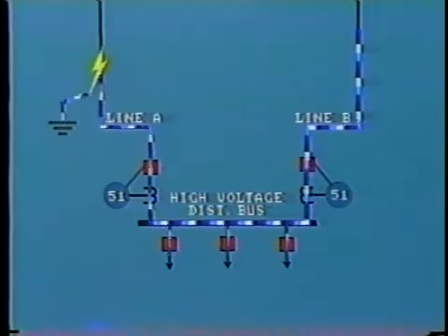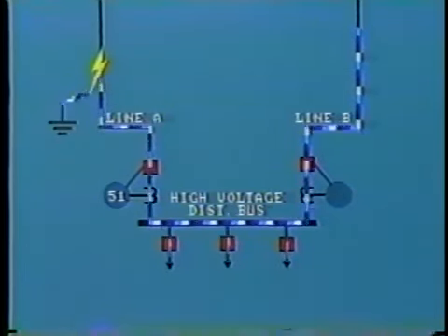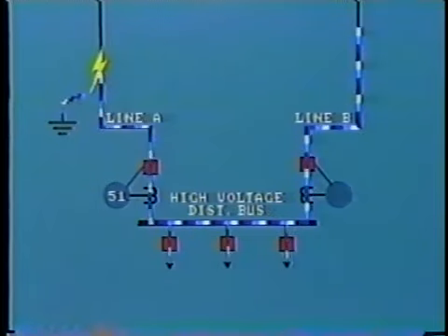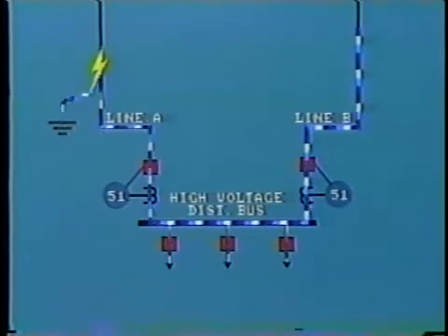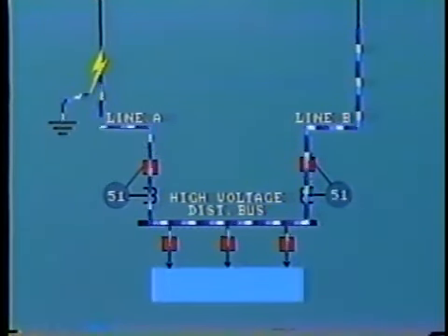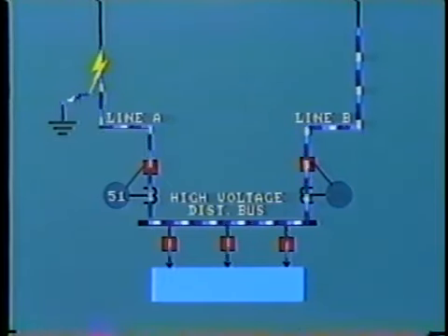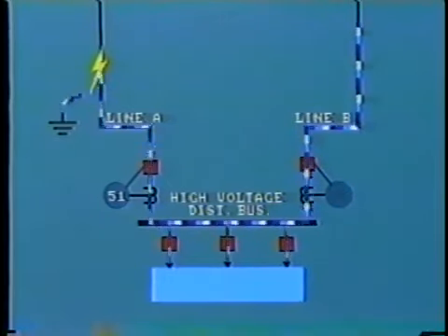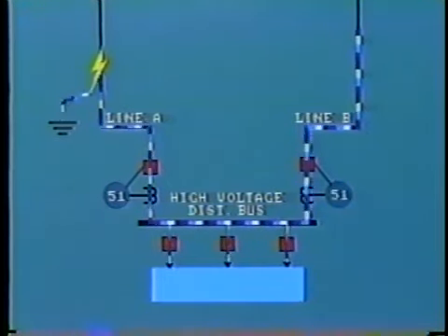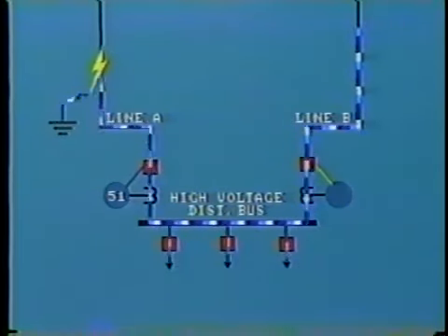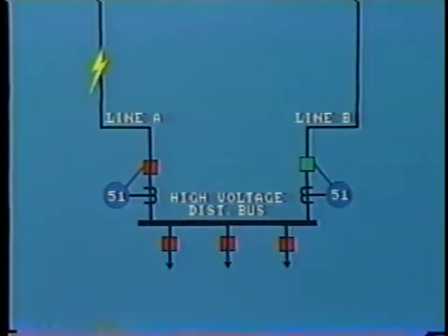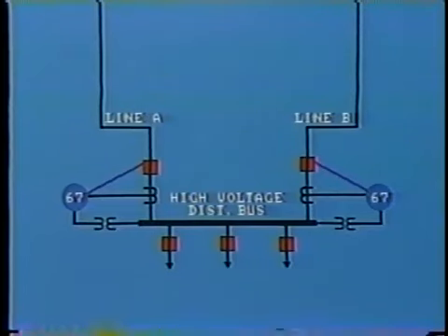Therefore, its own overcurrent relay will also sense the high-level current and commence the tripping process. In fact, line B is also feeding the distribution load and therefore passes greater current than A. If the B relay trips out line B, the substation is left without any power supply at all. We can avoid this by using directional overcurrent relays, device number 67.